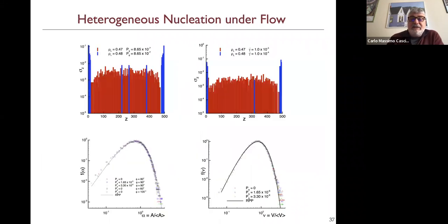So we can build a histogram of the sizes of these Voronoi polygons, and then compare them with statistical models for nucleation. In particular, one may expect that the spatial distribution of cavitation nuclei could be described by a Poisson process, and the distribution of the area of the Voronoi polygons for a Poisson process is shown by the solid line.